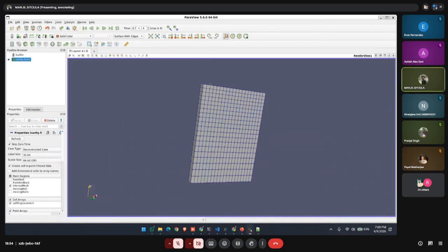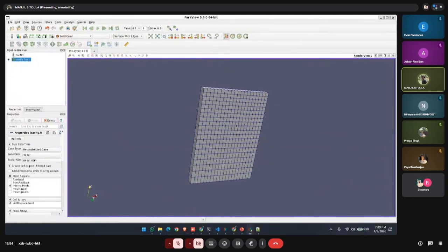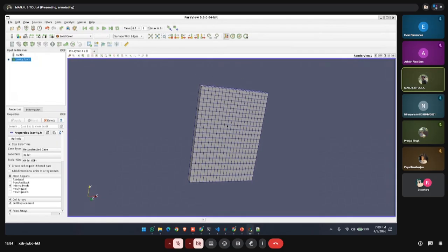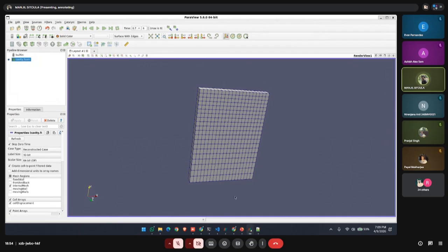This will be a different case. But our main focus here is how we can set up a case starting from a tutorial or from scratch, and then build it up as a dynamic mesh case. So we started from a tutorial case, the cavity, and then made a case like a piston simulation. This is the same strategy that is used in piston simulation, and we use a different type of solver. We might use combustion solvers, or other compressible solvers for our case.